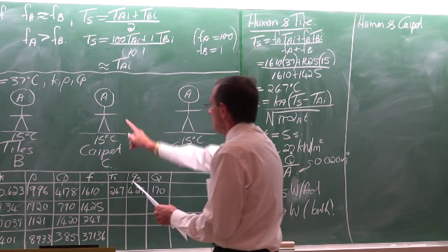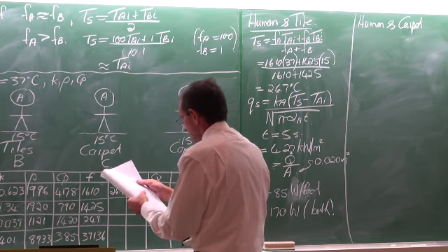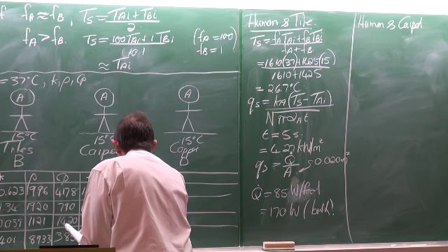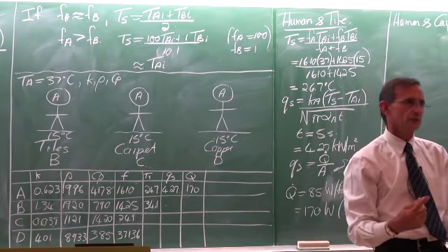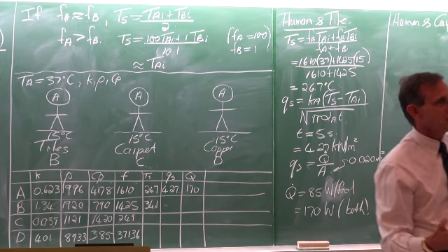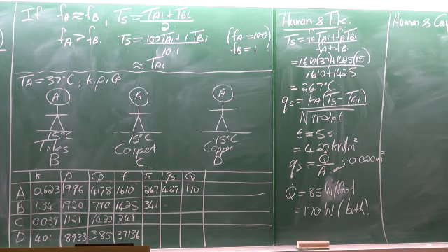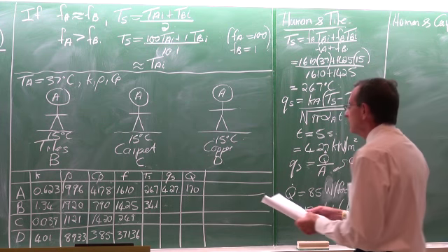So, for the carpet case, the surface temperature is going to be 34.1. So obviously that's the reason if you walk over the carpet you would say it is warmer than the tiles. The temperature of the tiles is 15, but the temperature you feel would be 34. And that is why you would say it is warmer.